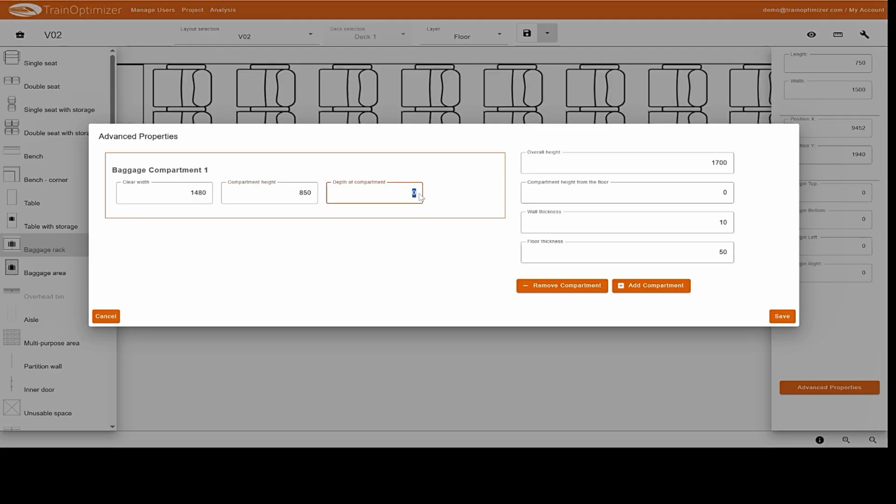The depth, on the other hand, does not correspond to the full depth of 750 mm, as there may be an electrical duct or ventilation duct at the rear. Therefore, only a depth of 600 mm is available for the bottom compartment. We can also deviate from the width of the rack if the rack does not consist of two vertical side walls but of sloping side walls.